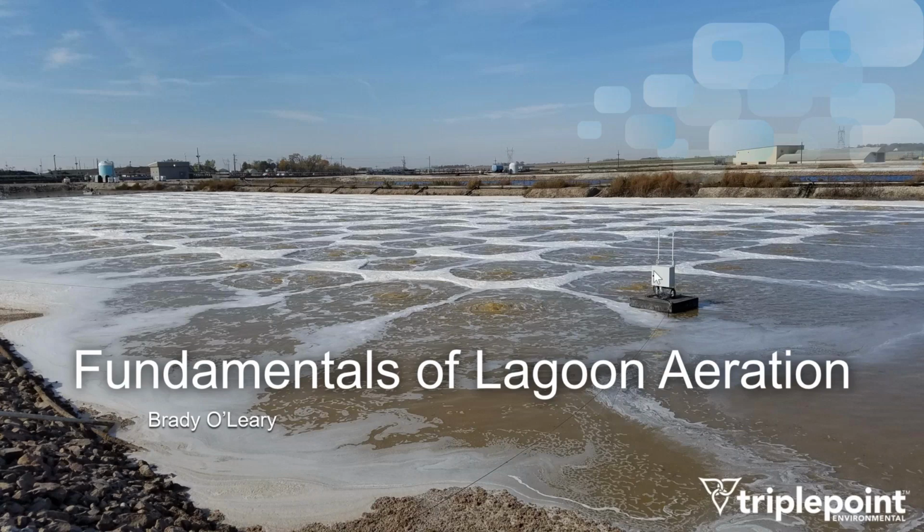We have a dissolved oxygen meter hanging out right here, and you can see that the bacteria is responding pretty well because it's creating foam. This basin had just started up, and when you see foam, it's an indicator of bacterial, especially young bacterial activity. So what you're seeing is a young biomass starting right here, which I think is pretty neat.